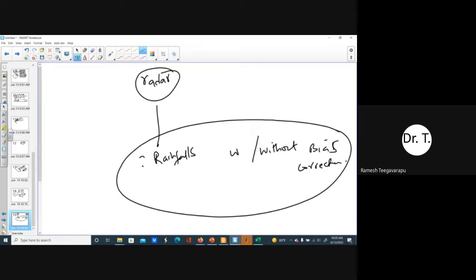Sometimes, if rain gauge data is not available in your area, maybe you can use the global products to do the corrections, because now the global products are available at 0.25 degrees. That's too large, of course, but in the absence of that, there are some GPCC data sets. There are data sets produced by Germany at the global level, or you can use IMD gridded data products, which I have used in one of the studies.